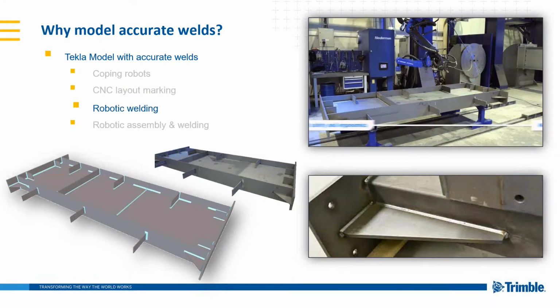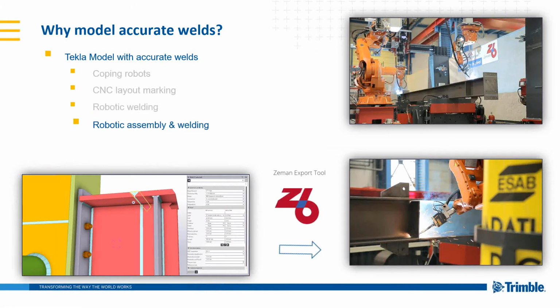Robotic welding, these are coming more and more into the industry, where these automatic welding robots will weld the pieces exactly as they've been modeled within Tekla. So all this is welded. If this weld in Tekla was, let's say, from the middle of the plate to the outside, that's the weld it will put on. It reads exactly the information in the Tekla model and exactly replicates that on the actual piece of steel. And then, of course, we have the robotic assembly and welding, where it picks up the plates, fits them together, and welds them together. Fully automated robotic manufacturing of structural steel parts.